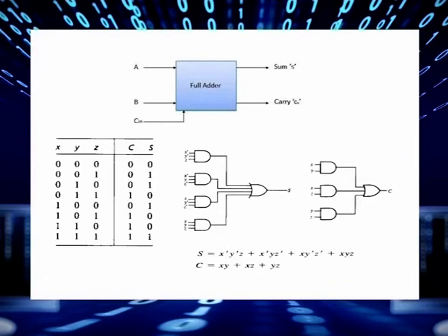As we have already studied half adder, and we know that half adder can add only two single digit numbers, but what about the carry bit? So this is a limitation with the half adder. Full adder is developed to overcome the drawback of half adder circuit. It can add two 1 bit numbers A and B and a carry C. Thus in a full adder we have three inputs and two outputs. This is the block diagram of full adder along with truth table and logic circuit.